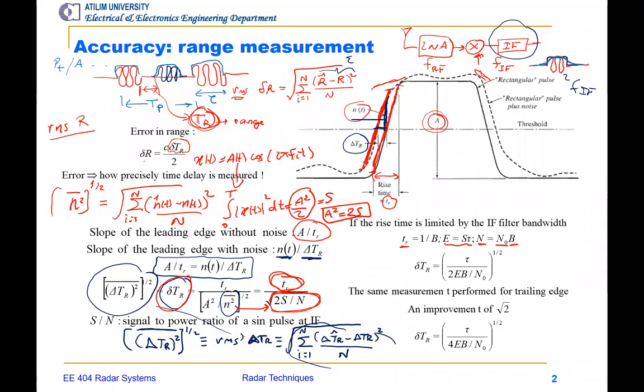For example, a smoothed version. This is due to the fact that there is no filter which can allow all the components of a rectangular pulse. Whenever we apply a rectangular pulse to a filter, to any system, we always get a smoothed version, because the frequency content of a pure rectangular pulse extends from minus infinity to plus infinity, which means that we have an infinite bandwidth signal.